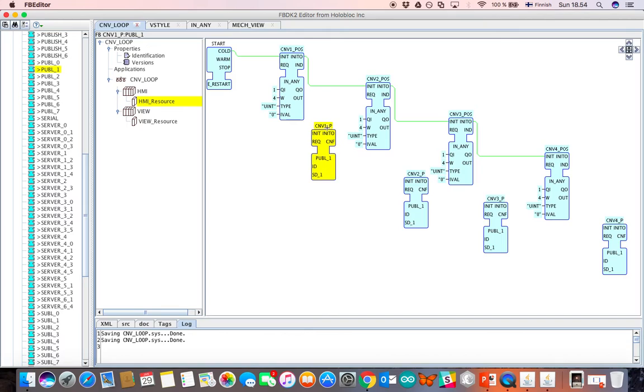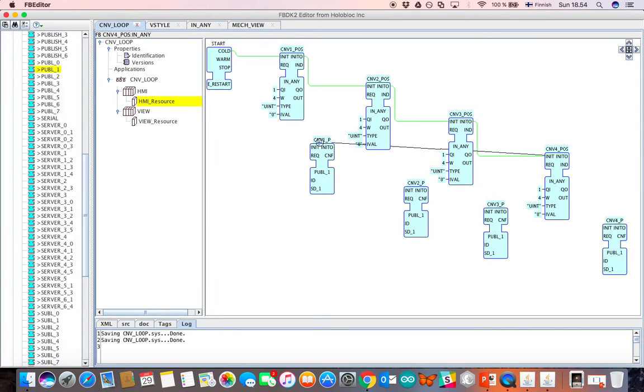Okay, what we can see, and as we develop applications using the IEC 61499 standard, is that we still need to initialize the blocks. One of the approaches could be to check what is the last INITO output that was not connected. So it is this INITO. Well, let's take the last not connected INITO, and connect it now to the first publisher block.